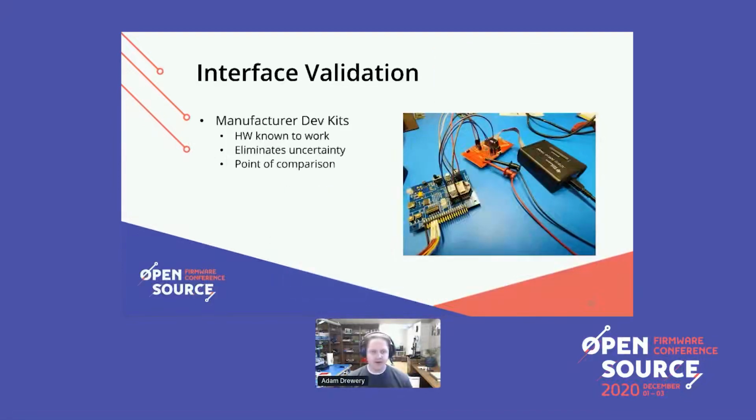And just at a higher level, you can also test any new peripheral. So in this case here, we're looking at the red circuit board. It's a CC1310 LaunchPad from TI, and that's interfaced there with a Digi modem. I really want to give a shout out to manufacturer dev kits. They're super important, probably your best bet if you're doing this kind of interfacing and prototyping, because it's hardware that's known to work, which eliminates uncertainty. But lastly, it provides a point of comparison when you're debugging your custom hardware.